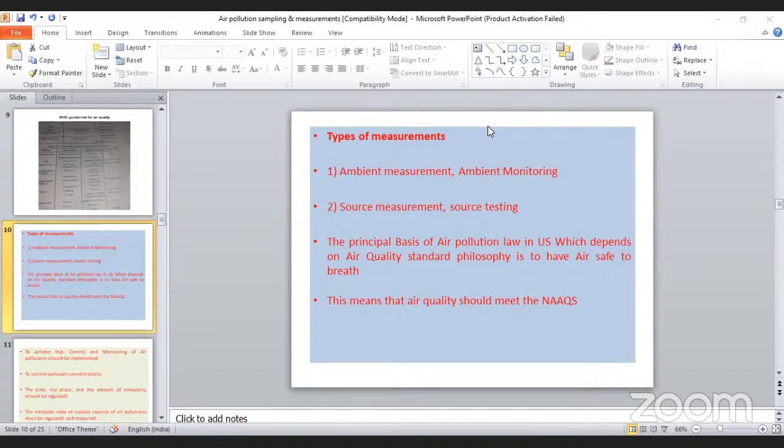In this method, a filter-based high volume sampler, whatever we have discussed, that is vacuum-based, is used. A vacuum type device draws air through a filter and retains the atmospheric particulates on the filter for future laboratory chemical analysis or weighing, that is wet analysis or gravimetric analysis.